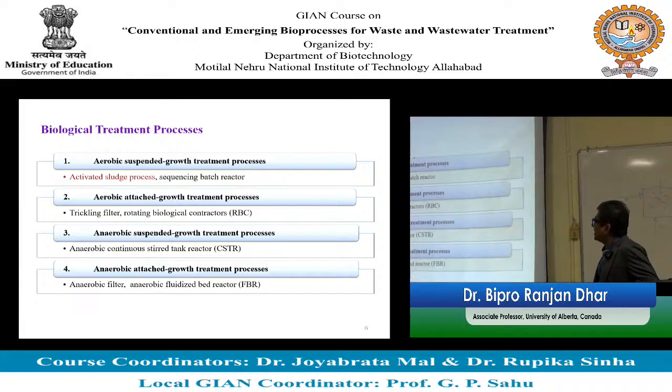So sometimes, to avoid clogging, another process is used where, instead of a packed bed of media, you have particles that can be fluidized within the system, okay. So there is no clogging. This is called the anaerobic fluidized bed reactor or bioreactor, FBR.